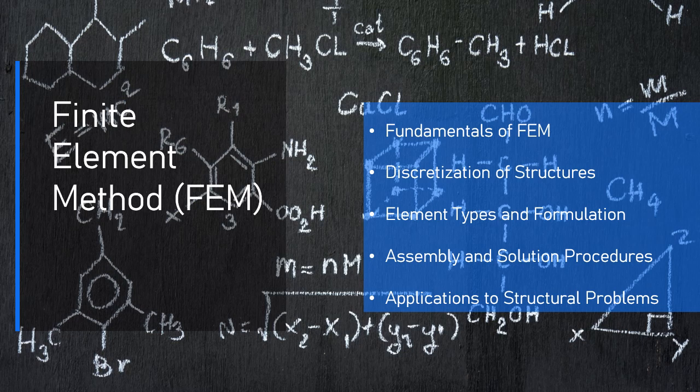4.7. Example of discretization. Consider a simple 2D beam subjected to a uniform load. The beam is divided into multiple beam elements, e.g., 4 elements. The following steps would be involved. 1. Discretize the beam. Divide the beam into smaller beam elements, e.g., 4 or more elements. 2. Assign material properties.